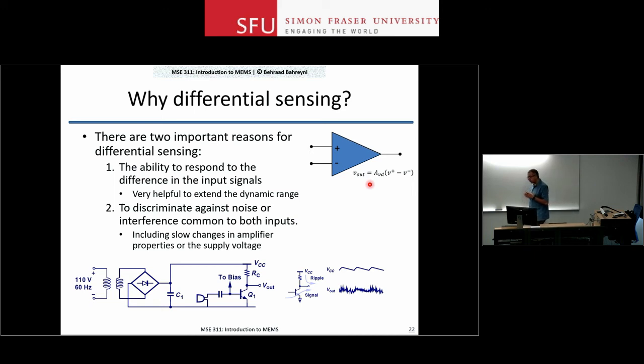Again, I'm sure you've seen examples of these before, right? So if you have an amplifier sitting far in the distance from your source, you can't take a pair of wires to connect, let's say, your microphone to your amplifier and take it across the room. Very few of you will do that. Why? Because if you do that, you will have a huge interference coupled to your lines.